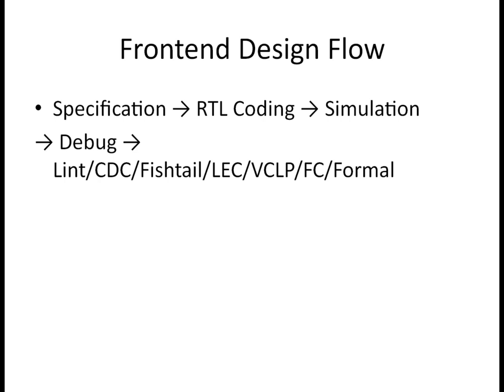where the design which we have decided should be correct till the end. So in that case, we are using two flavors of LEC. One is FEV light, that is called formal equivalence verification lighter version, and one is called sim to sim. So in FEV light, we are just checking whether the tool is going to read the RTL correctly or not. If there are any undriven signals, we'll clean those in FEV light. Once FEV light is clean, it is better to proceed for sim to sim.